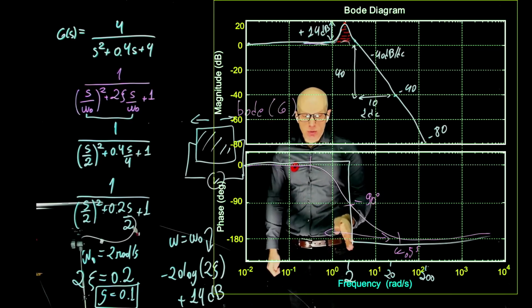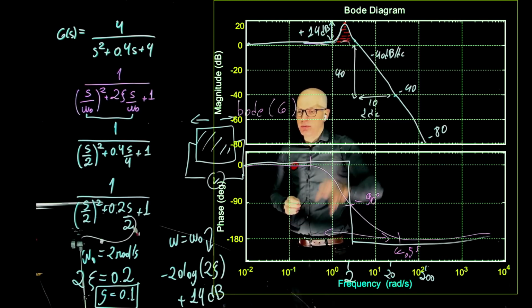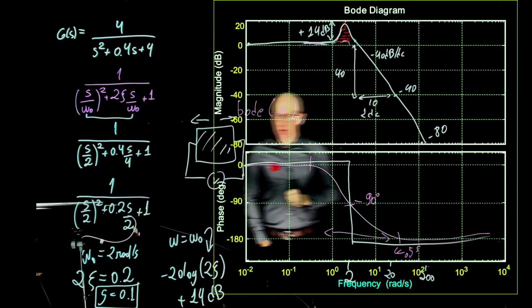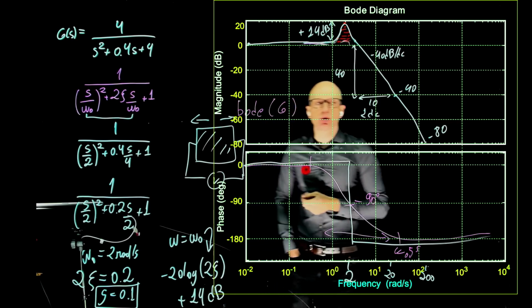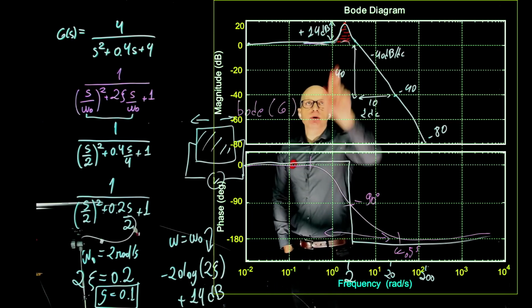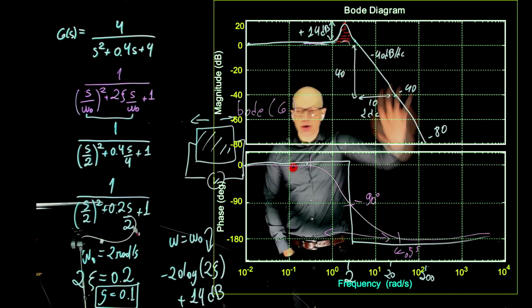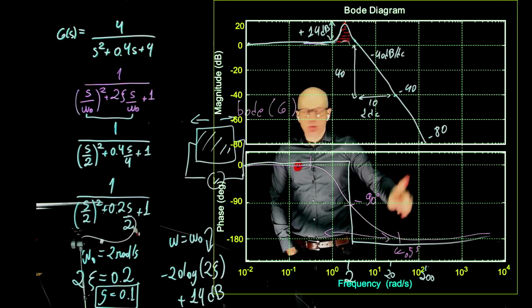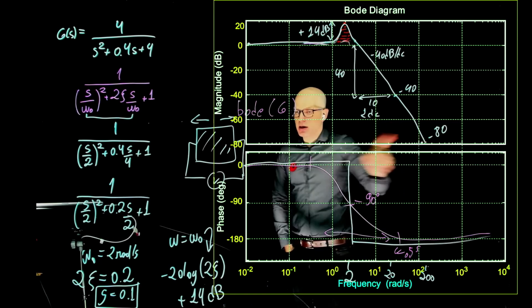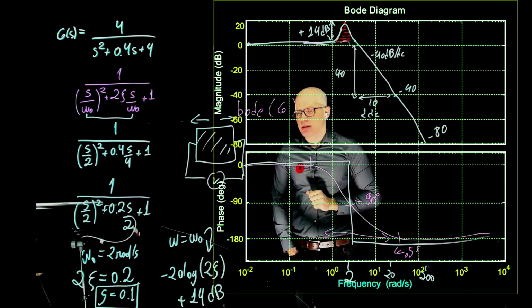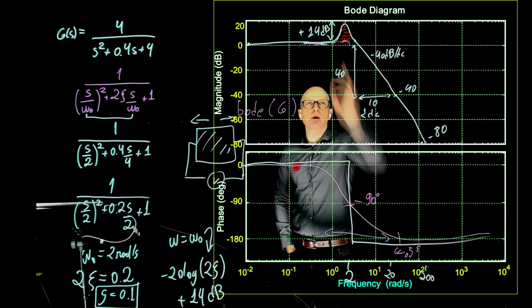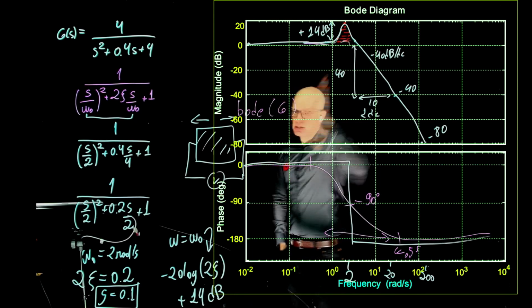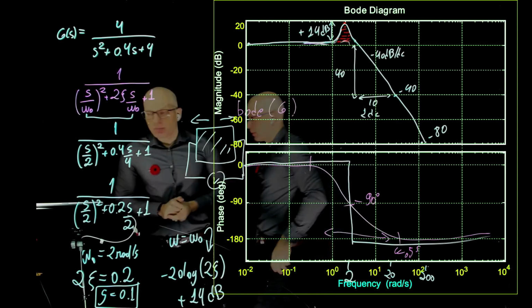In this particular case, we do want to operate near the resonance frequency, near the top of the bump here, and we want a damping ratio that is very close to 0. We can't achieve 0, but we can get close to it. In other cases, such as the bridge, we want to be operating far from this point, over here. A small input to the bridge, displacement input or force input, would create a small displacement because the gain is very small. It's negative dB. If you operate right there, then a small input creates a large displacement, and the bridge may collapse. In this case here, that's precisely what we want. We are creating motion from a voltage input.